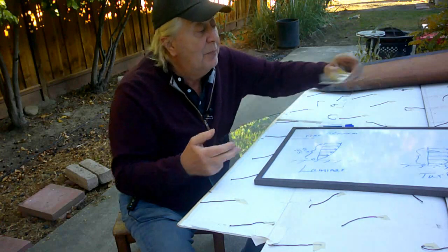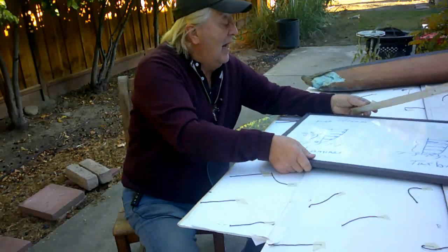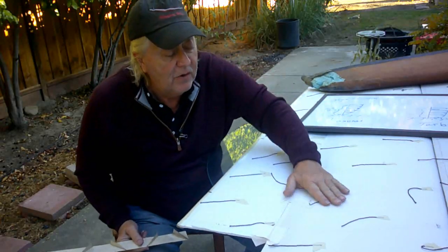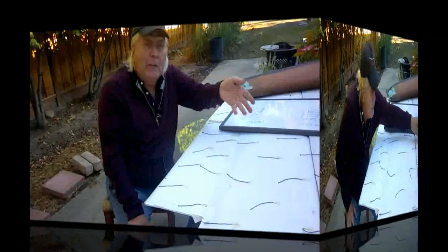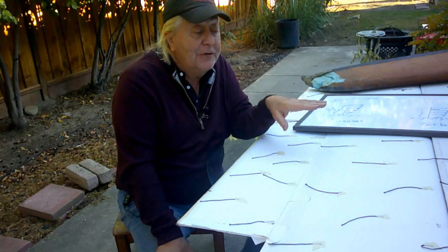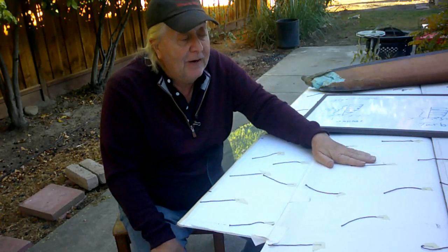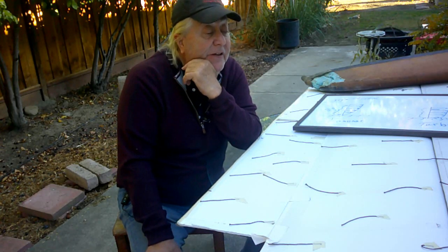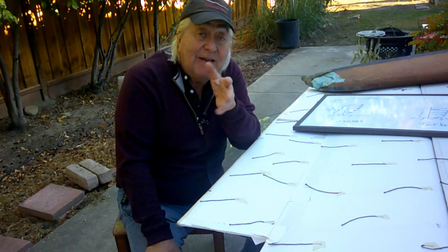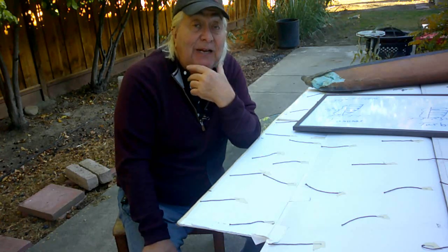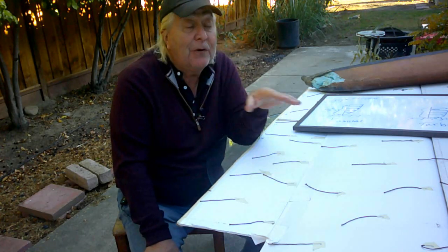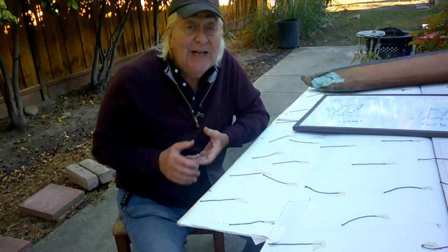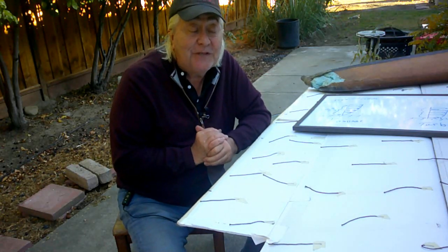First shot, I put it on here and discovered that the flow on the elevon was a little bit better. So I found that there is a spot where I can turbulate the flow and make it a little bit better on the elevon, and that got me from about 15 degrees of deflection on the elevon before separation up to about 17 and a half degrees. So I gained 2.5 degrees of deflection before the flow really started to separate back here. Well, that's nice, but it's not as much as I'm looking for. I'm looking for 20 plus degrees of deflection.